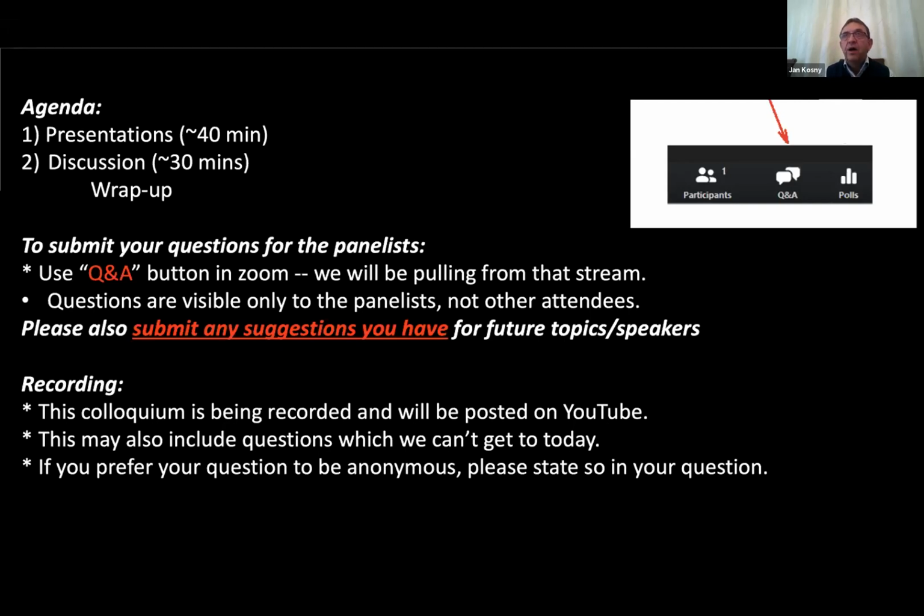You are adding to construction something which is highly impermeable and something which creates a huge delta T across the building envelope. So if you put this on the inside part, during the winter the whole outside part of the building is very cold. If you put this outside, you are exposing that internal part, for example during the summer, to condensation. So there are a lot of interesting processes which have to be taken into account. I can give you an example.